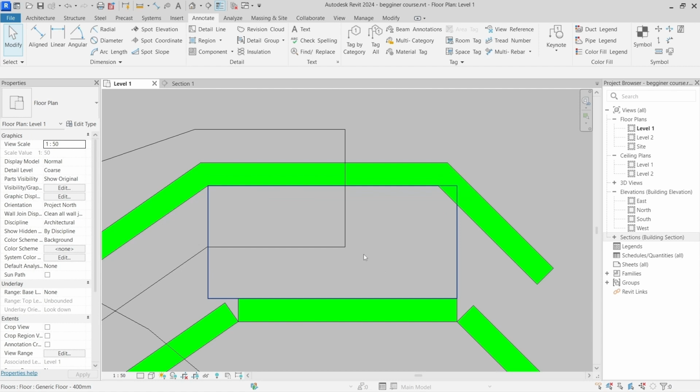So I have 3 elements in Revit which I can choose from when selecting. When I hover around here, you can see that now I have a preview for a detail line to be selected. If I hit my tab key now, I will switch through the things that Revit considers for the selection. So now I can choose my wall, and if I hit my tab key again, I can choose my floor. You can see that if I'm hitting my tab key, I am switching through different selection previews which Revit gives me for the selection.